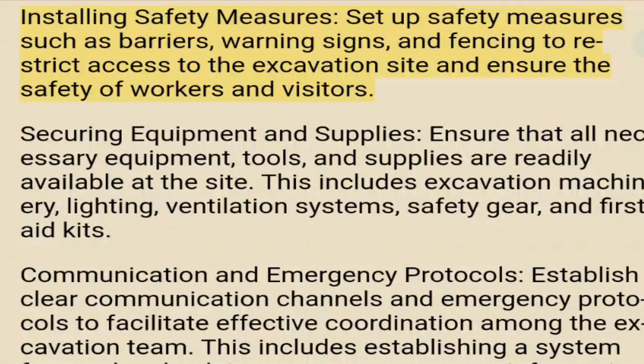Installing safety measures. Set up safety measures such as barriers, warning signs, and fencing to restrict access to the excavation site and ensure the safety of workers and visitors. Securing equipment and supplies. Ensure that all necessary equipment, tools, and supplies are readily available at the site. This includes excavation machinery, lighting, ventilation systems, safety gear, and first aid kits.